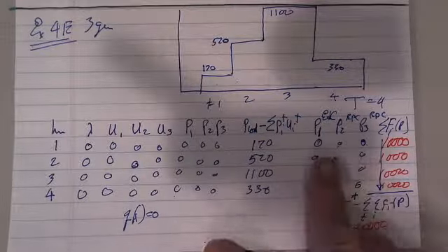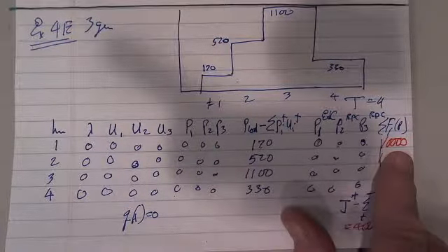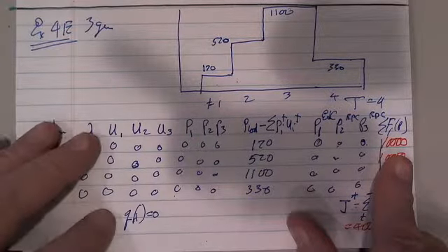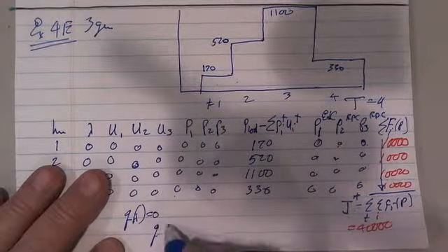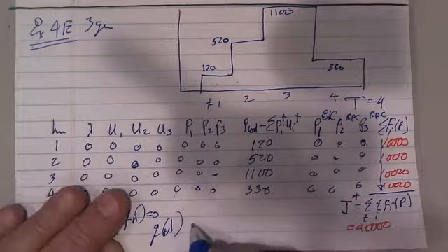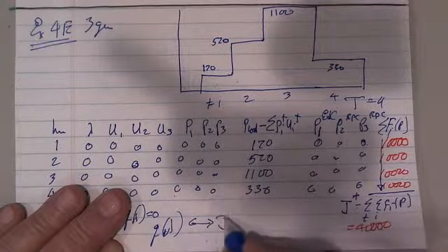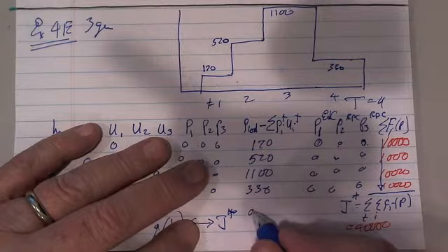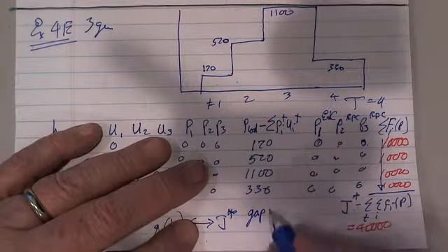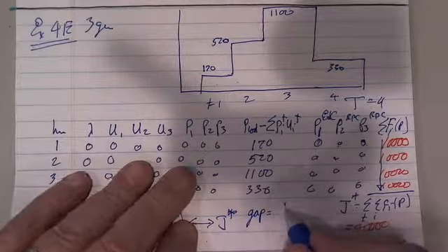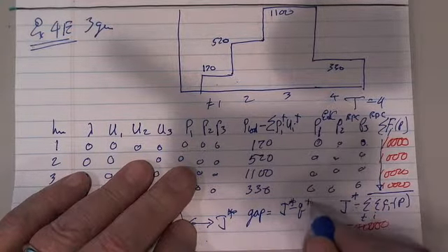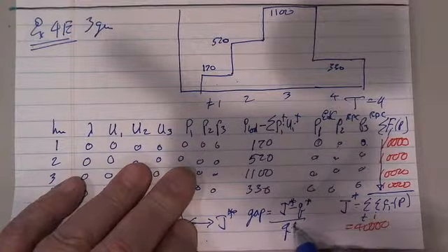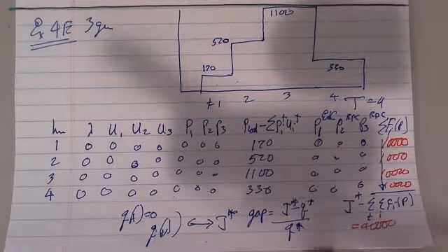As soon as you get an economic dispatch solution, then that starts to come down. Okay? And what you want is you want the Q of lambda to come over to the J star. And we created this variable called the gap. I should say Bertsekas and his crew. The gap is J star minus Q star over Q star. And it's not defined when Q is 0, obviously.